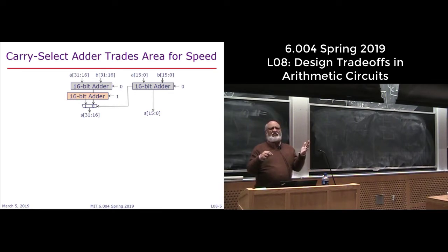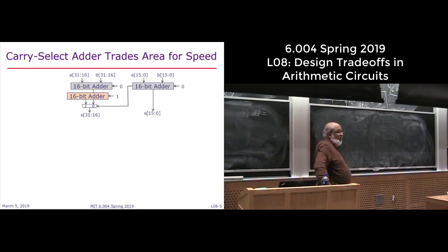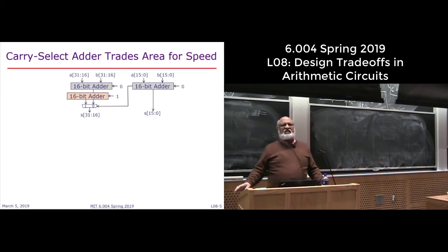Why is this a good idea? Because not every operation is sequential, things can happen simultaneously. So the worst delay has gone from 32 to 16 plus change. You have this 16, and a mux. A mux also always introduces a delay, of 1 or 2 gate delays.